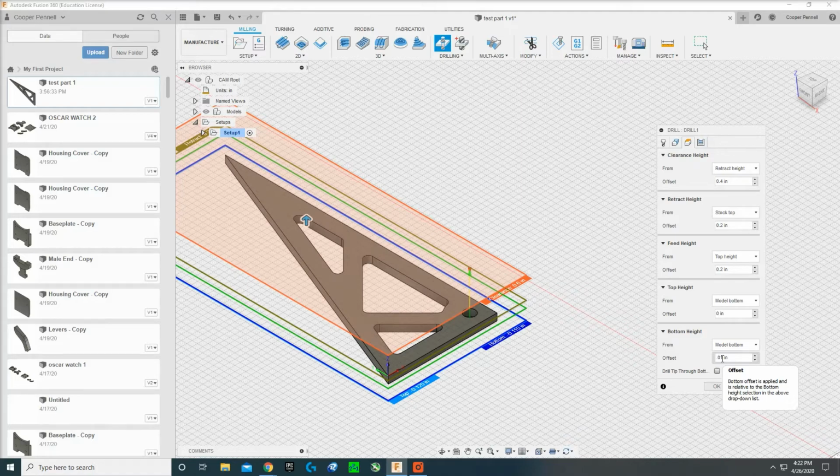So yes, if you do it correctly, we're going to be putting a little 1/100th of an inch indentation on the router table, and you'll see that the router table has so many marks on it from me doing this, but that way you ensure that you really get the drill holes to go all the way through the part.